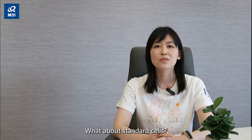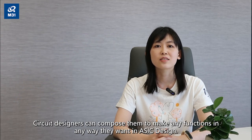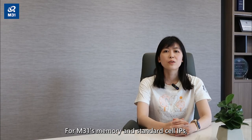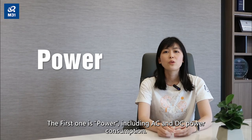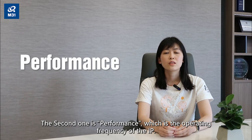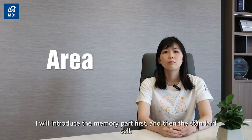What about standard cells? Standard cells are like living cells in electronic products. Circuit designers can compose them to make any functions in any way they want in ASIC design. For M31's memory and standard cell IPs, there are three key points that need to be designed upon customers' request. The first one is power, including AC and DC power consumption. The second one is performance, which is the operating frequency of the IP. The third is area. I will introduce the memory part first, and then the standard cell.